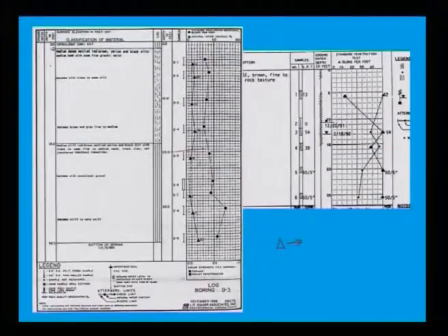Suppose there is a mistake in soil classification done in the laboratory. Suppose here it is silty sand, and at some depth you get some sand. Then it is not possible that over the depth the N value would be constant. Look here, N is 11, N is 15, N is 10, N is 15, the N value up to 18.2 is almost varying between 10 to 15. That means it completely cross-checks whether your laboratory tests are correct or not.